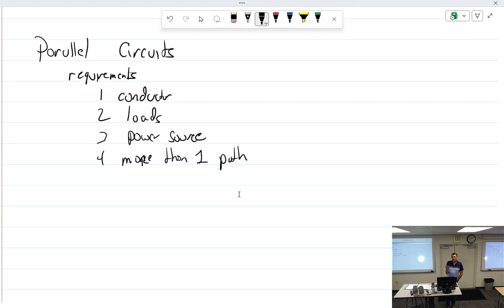Within a component, you might find series or series parallel circuits, but outside of a specific component within the aircraft, almost everything is going to be a parallel load. Everything is parallel. Like I showed you before, you have one wire that's going to run to the bus, then off the bus, you're going to split off everything else, even if it's one switch to operate something. So let's see, we have the bus.